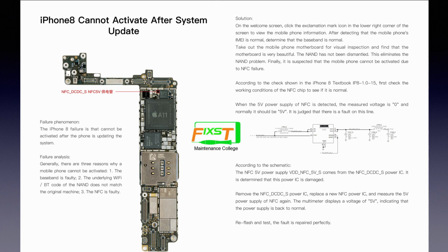So we take out the motherboard to check it. This motherboard is also very clean, and the NAND has not been repaired, so it's not a NAND problem. It shows that the NFC has some problem. So we need to check the working condition of the NFC. First we need to check the power of the NFC.